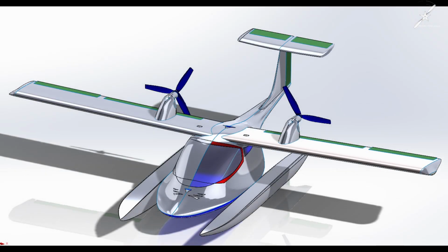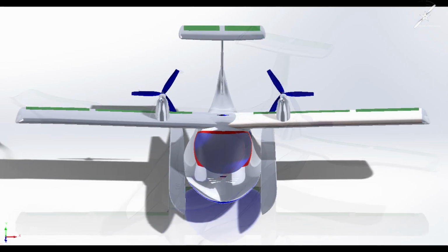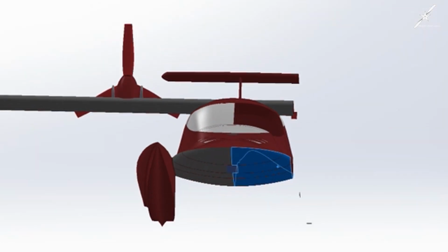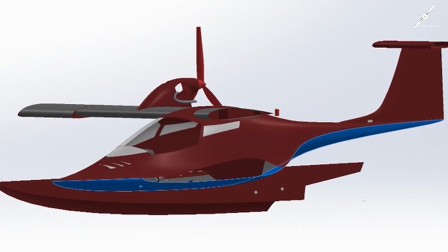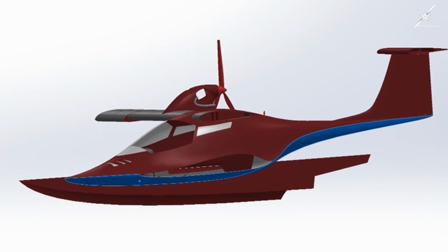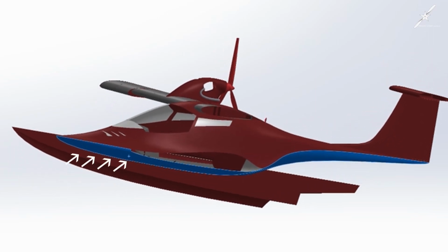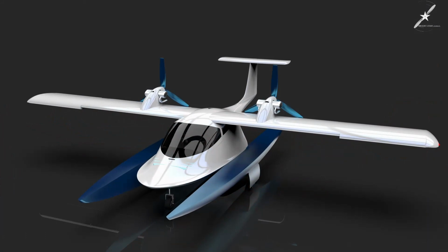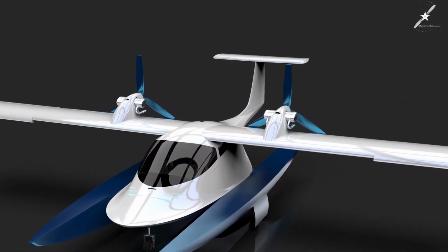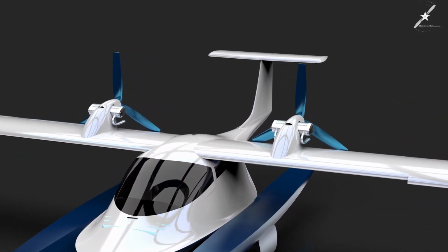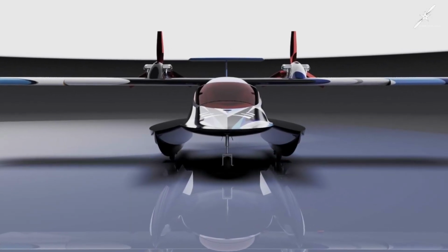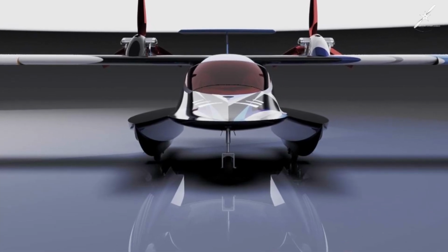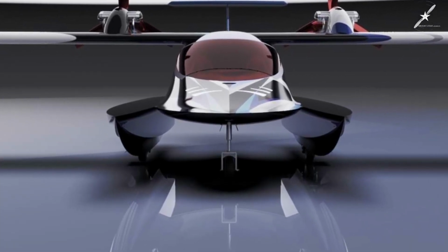The reason for the change was because a couple of viewers felt the large flat surface on the bottom of the fuselage would, at low speeds and high angles of attack, create too much dynamic pressure on the bottom of the aircraft. Although I do agree that at low speeds and high angle of attack there would be a fair amount of dynamic pressure, I personally felt the aircraft had enough control surface area to manage this. Also, it can be a good thing as the pressure causes a type of lifting which will help us get